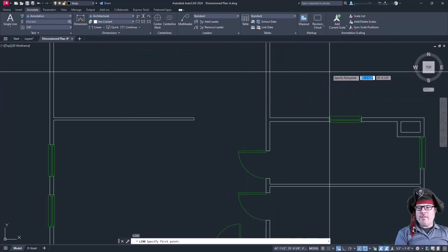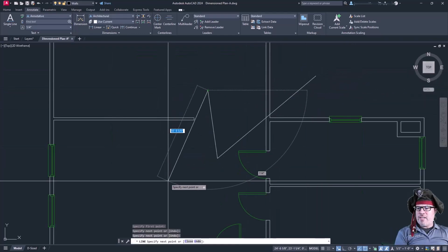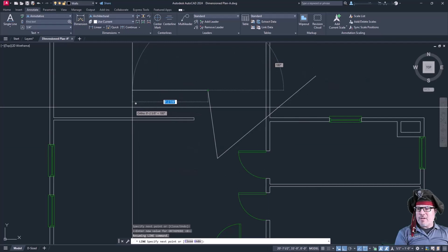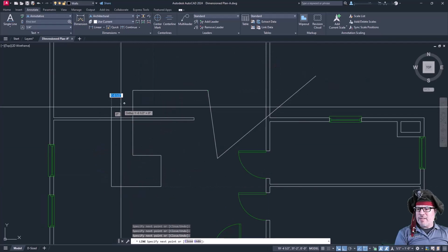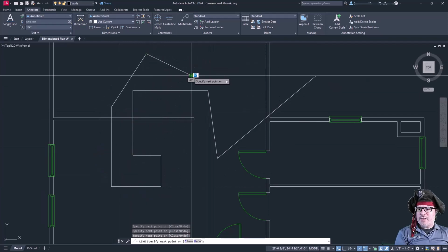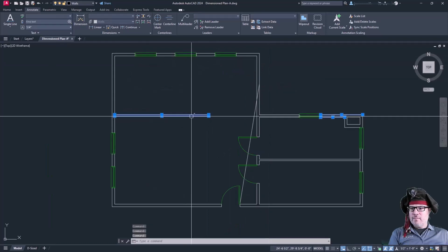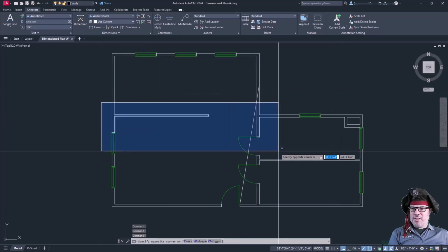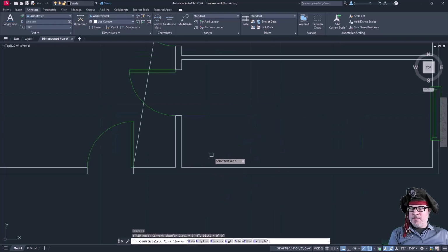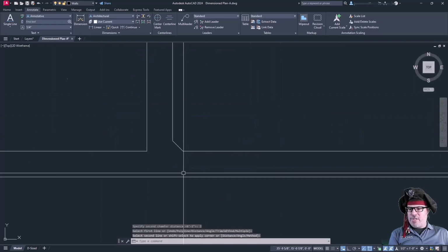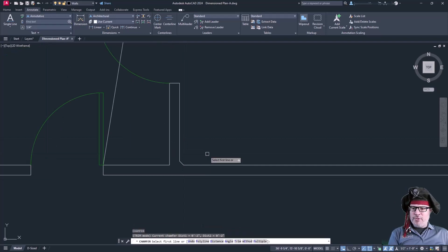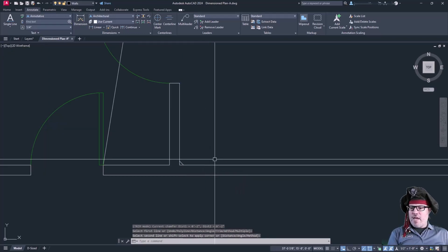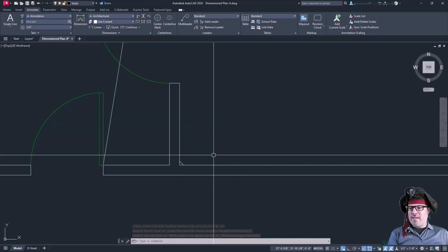In any drafting command, hold down the Shift key to enable ortho mode temporarily without turning it on permanently. Release Shift and it's back to non-ortho mode, whether individually selecting or using crossing or window selection. While in the chamfer tool, pick two adjacent lines and it will chamfer those together. Also in the chamfer tool, hold down the Shift key and it reduces the angle back to 0.